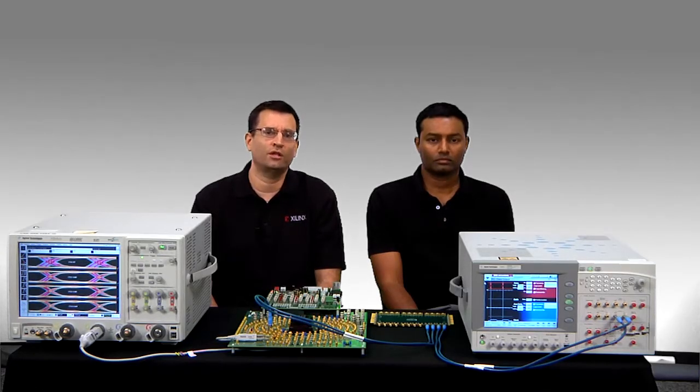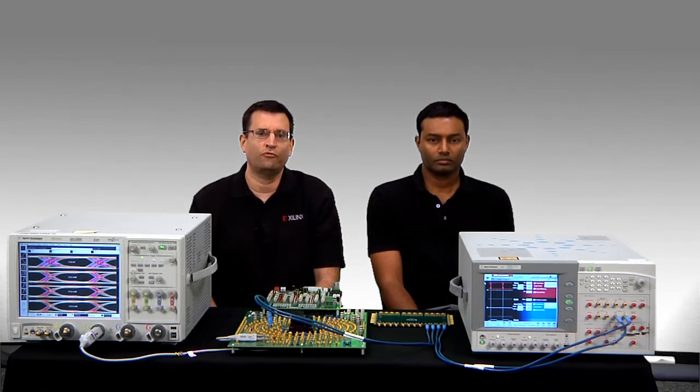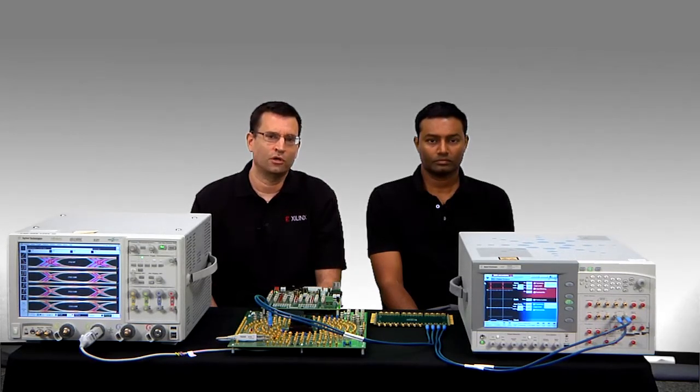Today, we have shown you how to use the UltraScale SelectIO CTLE capability to optimize the DDR4 link margin. We also showed you how to simulate the impact of CTLE on your system before designing your printed circuit board. Collectively, this methodology will ensure excellent operating margin when designing high-speed interfaces like DDR4.